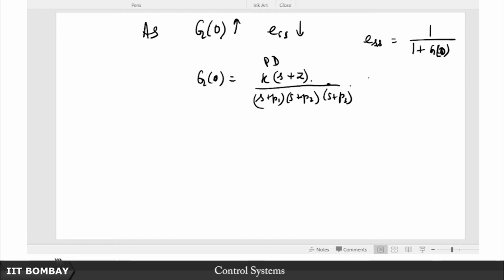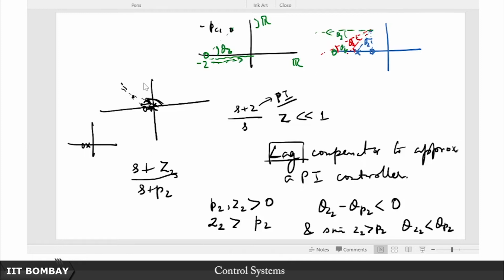And now instead of having that S plus epsilon, let's say this is S plus 10 epsilon. Now remember, if epsilon is very small, then in so far as the value of 10 epsilon is concerned, looked at from the vantage point of a closed loop pole, it will hardly make any difference between epsilon and 10 epsilon.